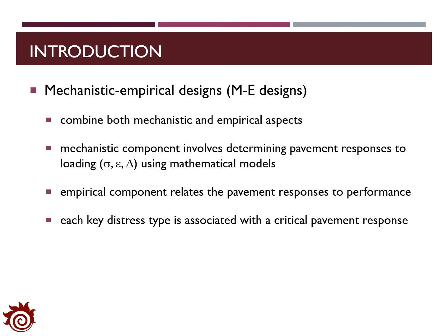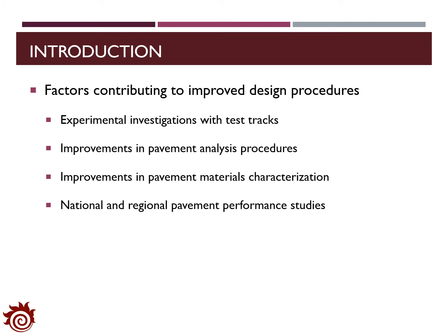The ME design will actually combine the advantages of both mechanistic and empirical models. We know that in pavement design, it's very important for us to identify the distress types with respect to the critical pavement responses. In the ME design, we will use the mechanistic model to determine the pavement response to loadings with some mathematical models. On the other hand, we will use the empirical model to relate the pavement response to the performance of the pavement structure.